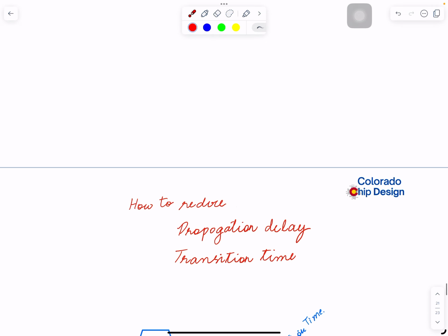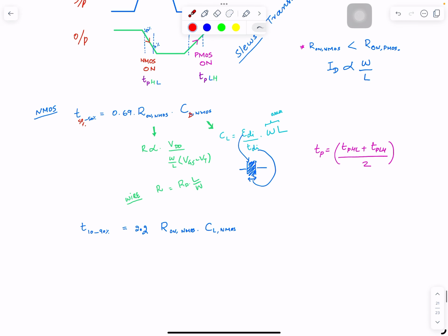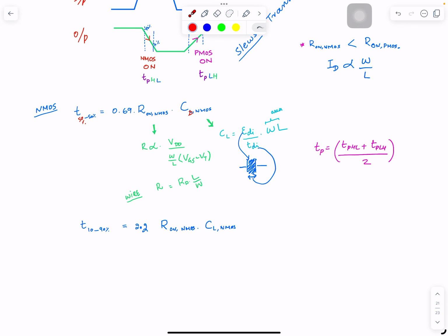They will have some other effects which we will talk about in future videos. So if you want to decrease capacitance, you need to make the dielectric thicker, you need to use a material with low permittivity, and your width will need to be smaller. So here you have factors fighting with each other.